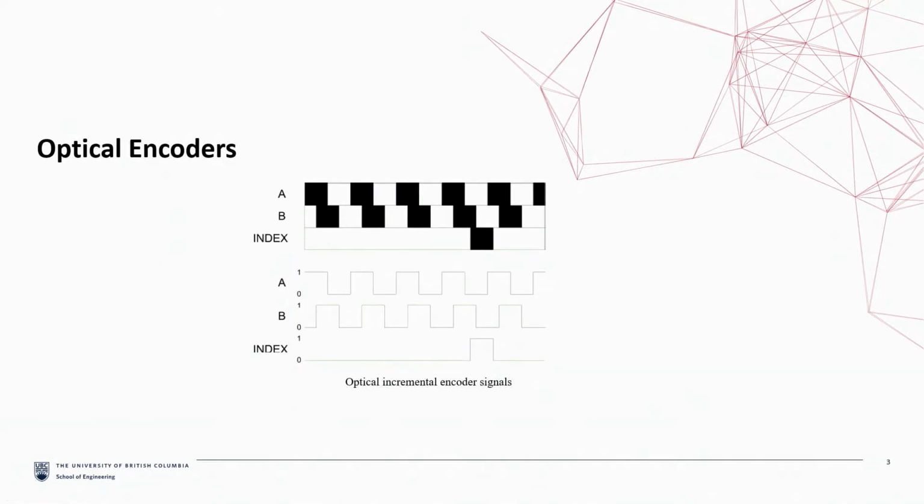The encoder used in the Quanser servos comes with three radial patterns of A, B, and the index. The A and B signals correspond to 512 lines on the disc, which have a 90-degree offset. The lines are equally spaced, and as the shaft rotates, the index C signal occurs once per revolution, and it is used as a reference value for the calibration of the system.